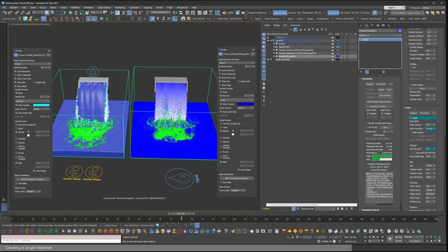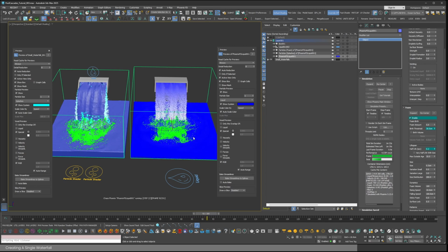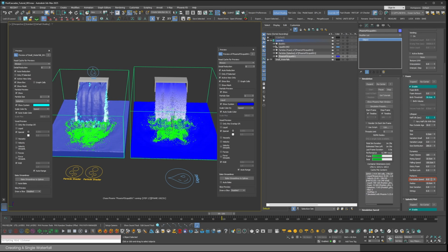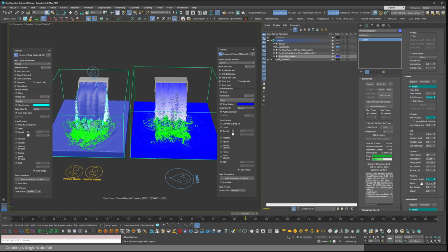Seems like in the simulation on the left, some patterns are appearing. In nature, these are caused by the upward motion of the fluid, which pushes the foam away, creating these circular shapes. You can reinforce this effect by increasing the pattern formation speed. I'll set it to 0.5. And I guess I can make the pattern radius a bit smaller.